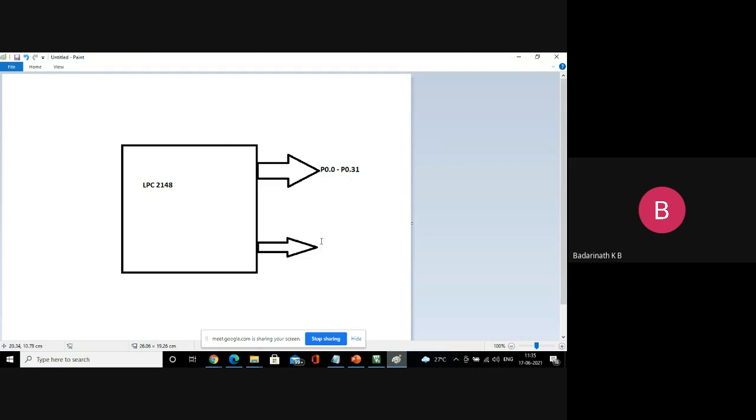All the pins are available there. So here, what are the pins available for me? P1.16 to P1.31 is available here. So these are the 16 pins, and another 29 pins here. Now, I want to, let's say, use one of these pins to perform interfacing to the external devices. Whenever we want to perform interfacing to external devices, what are the things you should be able to take care of? You know how to build a project. Let's say I am connecting a simple experiment to start with. I want to interface an LED to a microcontroller. What is the first thing you have to do?